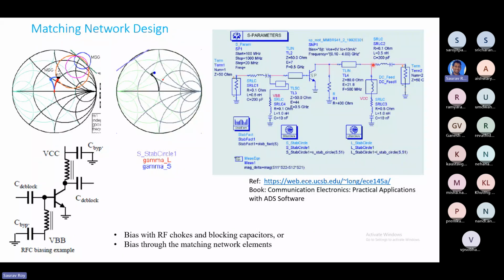Should not come that side, load side. So that's why this is the load. This is a DC block capacitor, which is also represented as a RLC equivalent, which is 200 picofarad high capacitance. So as you see, all of them has been represented like this because they considered a very realistic case. Any capacitor you take, it will come with some parasitic values that we can actually consider.